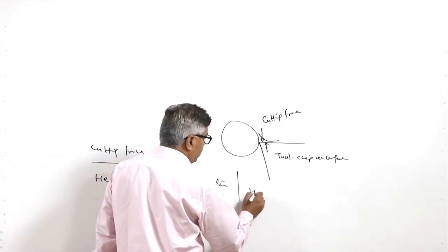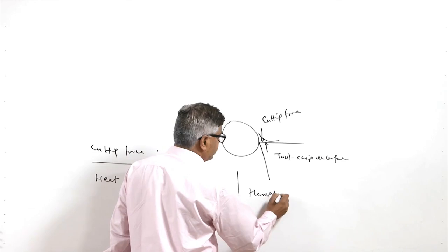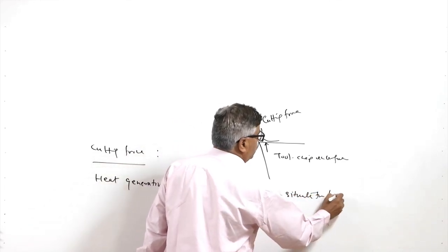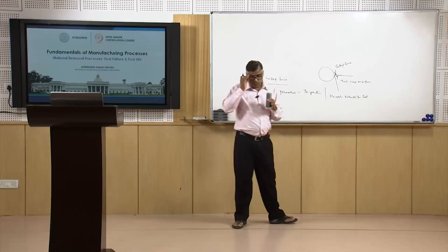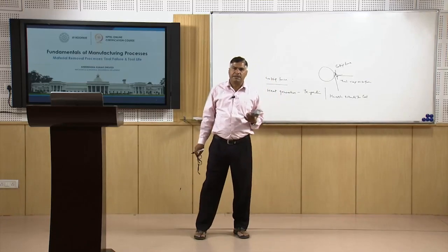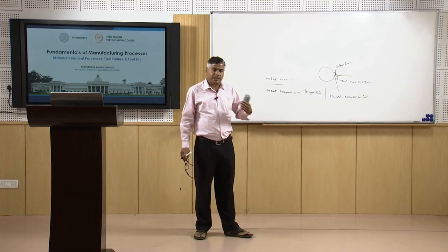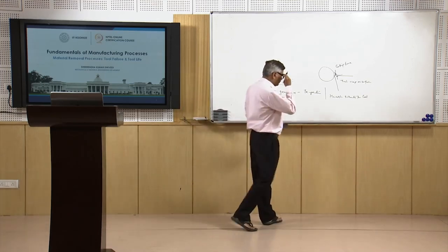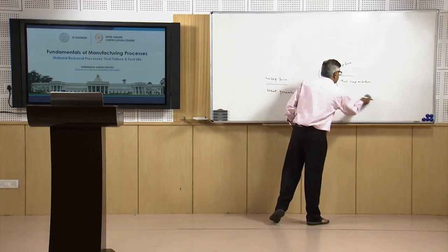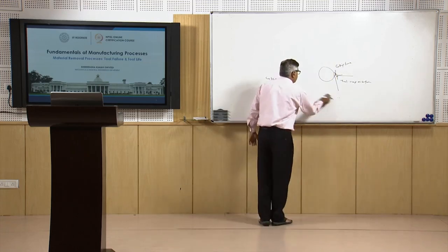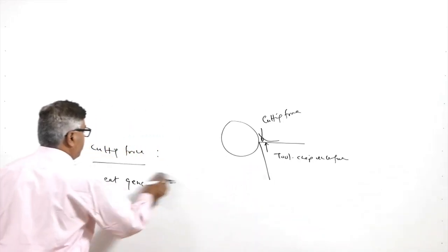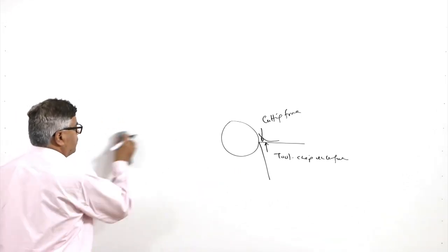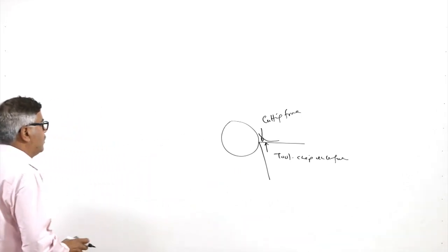This leads to the development of a very harsh situation for the tool to survive, because the tool has to sustain the forces generated during machining as well as the heat, causing the rise in temperature of the tool. These two abnormal conditions, the cutting forces and the rise in temperature, lead to the failure of the tool.